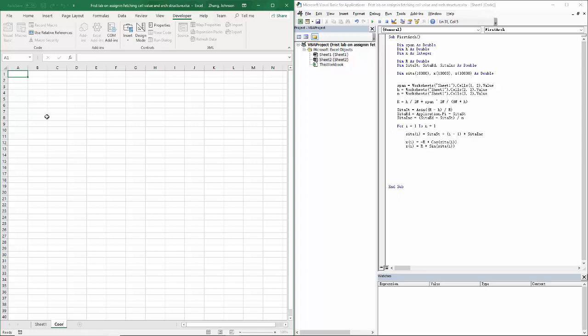So we're going to store the coordinates in here, and then we can also create another one by changing the name to members. Okay, so members in here. These coordinates we're going to store in here. Column number 1 is going to be the x coordinate, and column number 2 is going to be the z coordinate. Once we get this data, you can just copy all these coordinates and dump them into the Autodesk Robot, and it will generate all these nodes automatically.